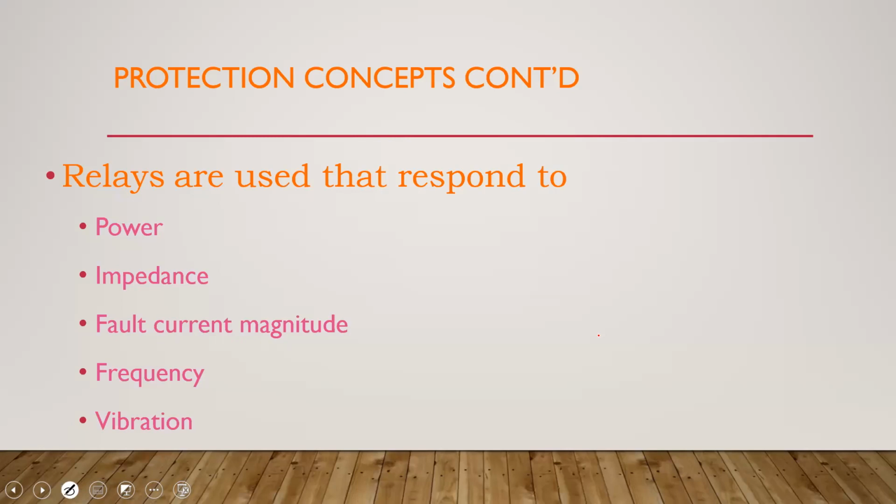You have frequency deviations, but remember, coming back to power systems now, we want to have a reliable supply, and at certain standards. So we must know that when we plug our equipment in, we're operating at 50 hertz, not 50.8, not 51, not 49.8 or 49.3, but 50. It sounds like you're willing to round off and tell me that there's nothing wrong with it. But anyway, 50 is 50, right?